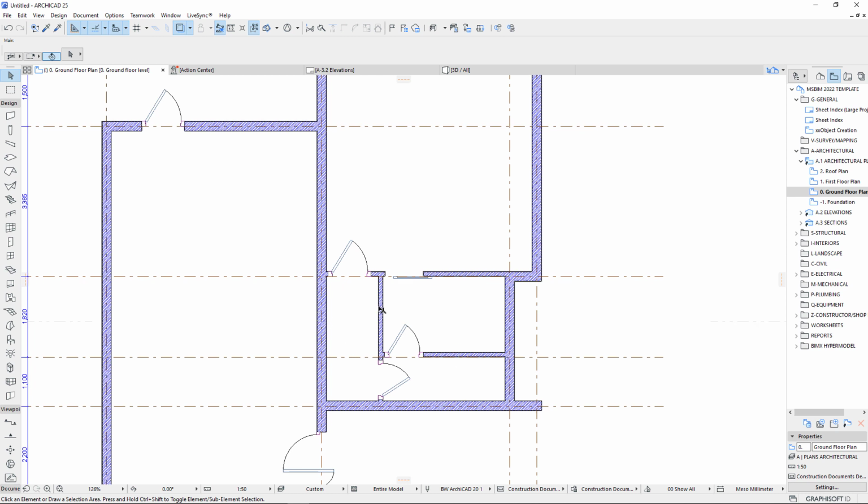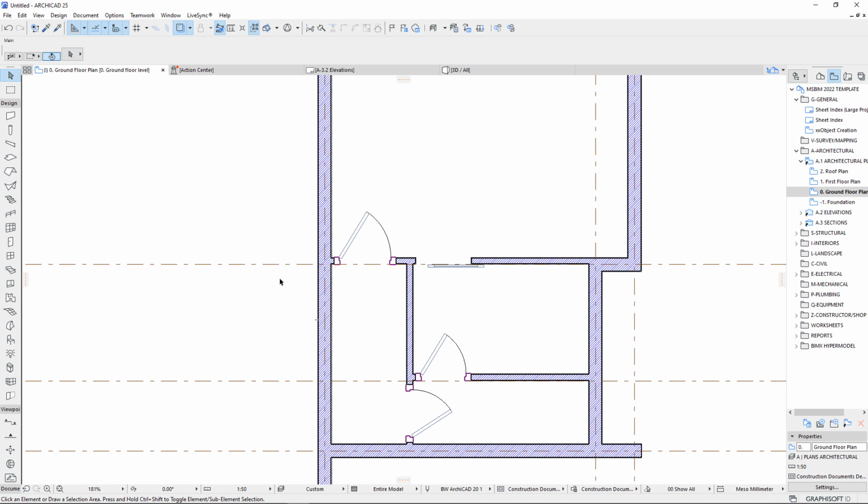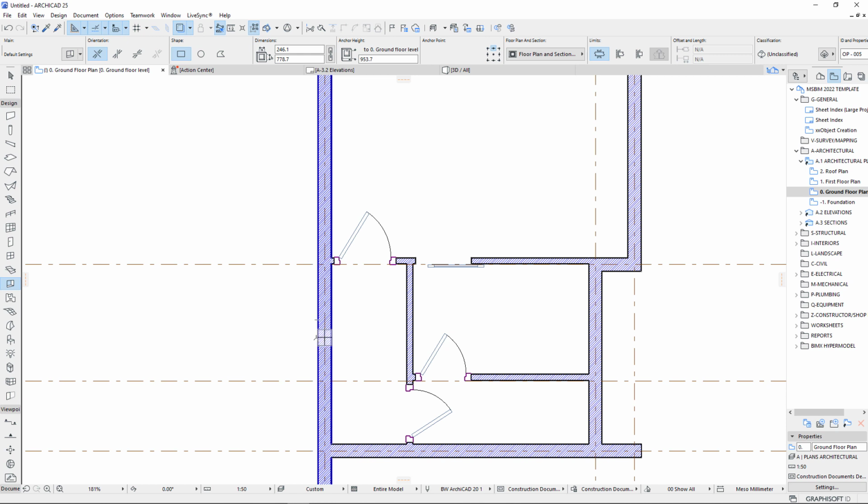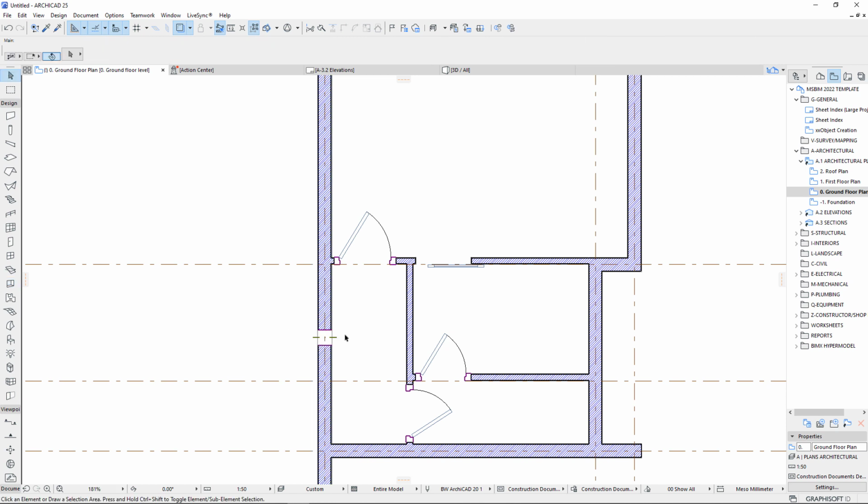To access all these areas, you need an opening here. So there are different ways of doing it. I can use a door, an opening for door or for windows. I can also use an opening tool. We have an opening tool in the latest version of ArchiCAD, where you can just click that. But the problem with this one is addressing the issue of material on the surfaces. So I'll go with the door